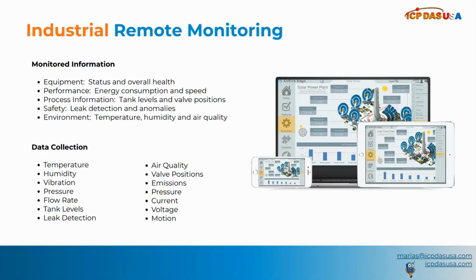Our digital input modules are used for getting the status of equipment being on or off, push buttons, and monitoring pulse outputs. Our digital output modules are used to drive relays in unmanned aerial vehicles, drive alarms, trigger the shutoff of equipment, and more. Our PWM modules are used for fine-tuned motor control, and our high-speed counters are used for counting encoder pulses to determine the positions of machinery and robotics.